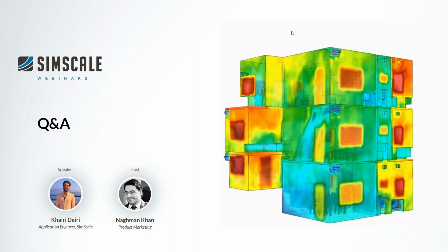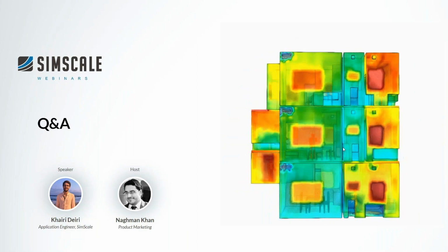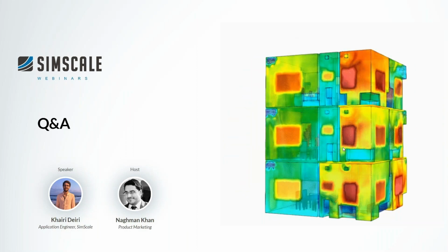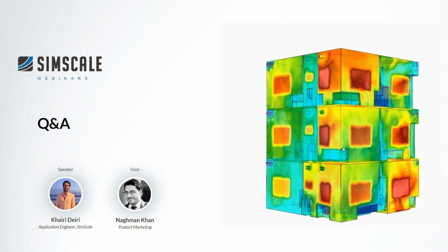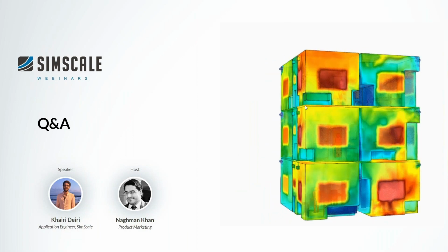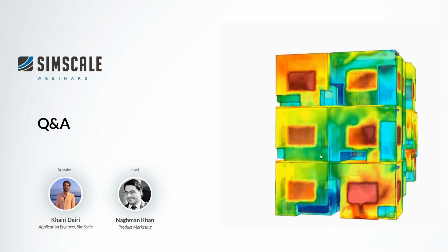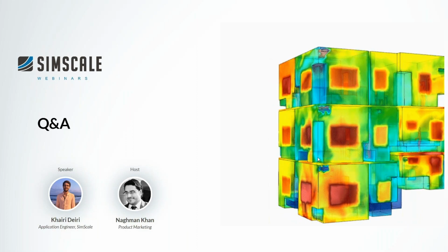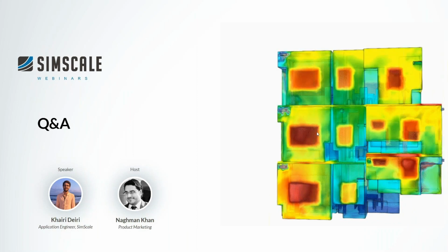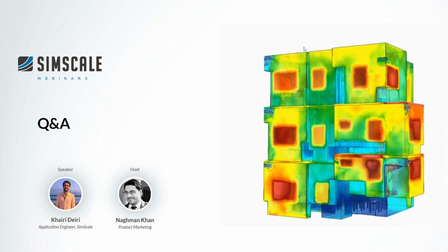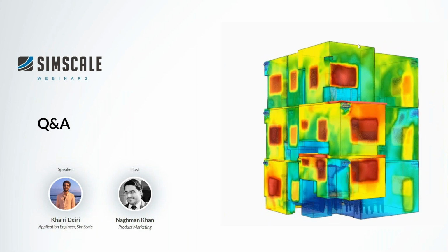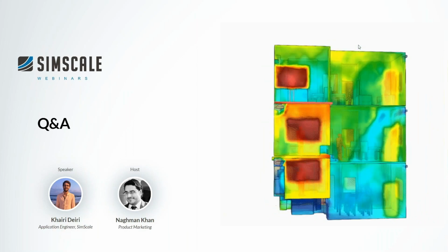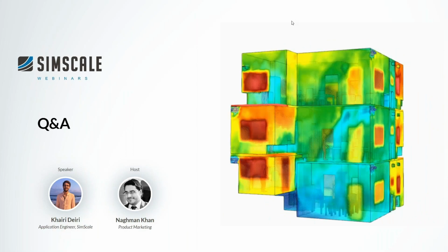Yes, especially for Rhino and Revit, we do have native support for these formats. For DWG, we just need to understand that SimScale allows uploading CAD models that are three-dimensional. So as long as your CAD is three-dimensional, you can import these CAD models into SimScale directly. It's also important to note that we do support generic CAD formats like IGES, STEP, and ACIS as well.